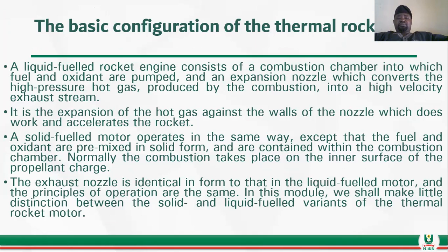A liquid fuel rocket engine consists of a combustion chamber into which fuel and oxidant are pumped, and an expansion nozzle which converts the high pressure hot gas produced by the combustion into a high velocity exhaust stream. Now, it is the expansion of the hot gas against the walls of the nozzle which does work and accelerates the rocket.